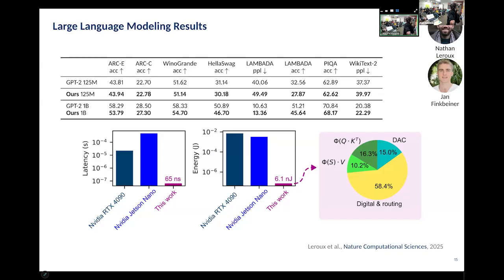Well, the design was analog, so each gain cell is storing one element of the projected token. And they're not big cells, they're 2T0C, so they only need 2 transistors. Oh, I see, similar to the circuit before. Yeah, I think the circuit we had before was a design using actual silicon, but doing this with these low leakage transistors is something that we haven't fully explored yet.